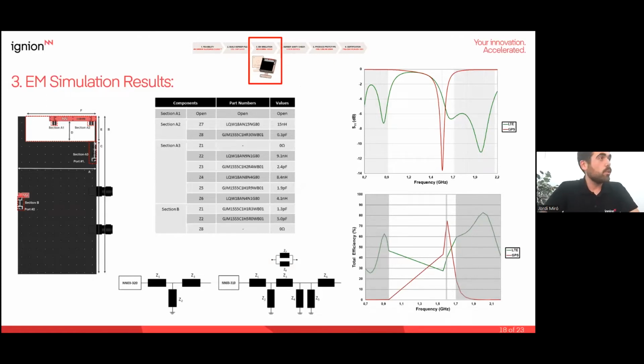But then we go to the electromagnetic simulations for the example we are following with the design journey. As you can see in the slide and also in my camera, we follow all the design recommendations made by our team. In case of antenna selection, the Trium Extend, we selected the Duo for GNSS. We put the recommended clearance area as well, the patch layout, the bill of materials, everything implemented following the design recommendations.